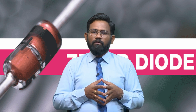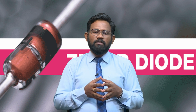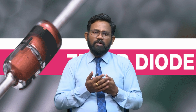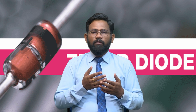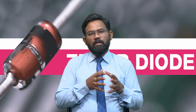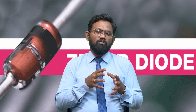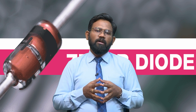So, our Zener diode finds its application in clipping circuits, where it clips or removes part of the AC cycles, either from the positive half, the negative half, or from both parts. So, these are the various applications. This application, the clipping circuit or clipper, we are going to study in the coming classes, and in the coming lectures we will study in detail the application of Zener diode as a voltage regulator, because these two applications of Zener diodes are very important and widely used in different electronic circuits.